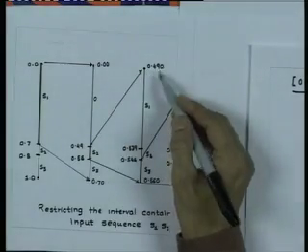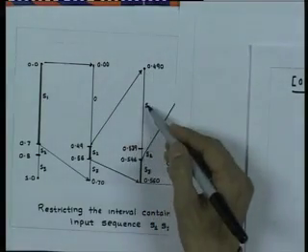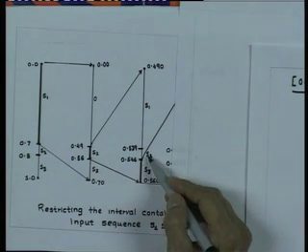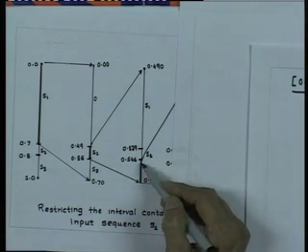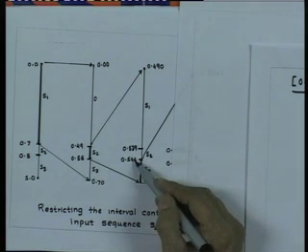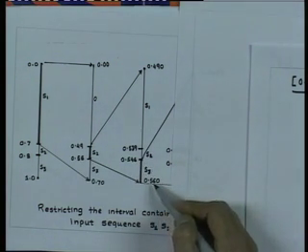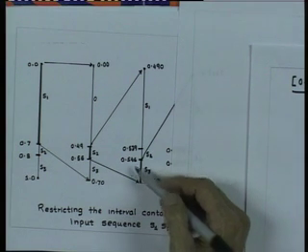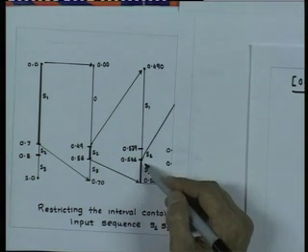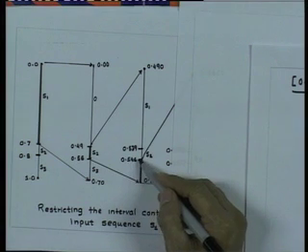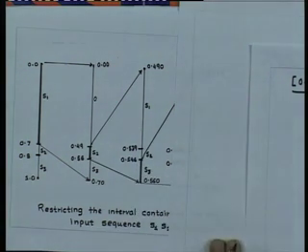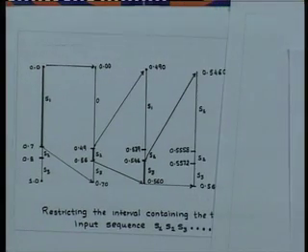So, 0.49 to 0.539 will correspond to S1, 0.539 to 0.546 will correspond to S2, and finally 0.546 to 0.560 will correspond to S3. Now, again if the third symbol is S3, the tag will be restricted to this interval, which is between 0.546 to 0.560, which can be subdivided further as shown here.